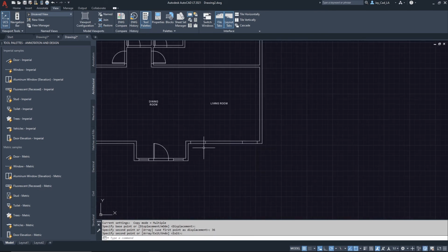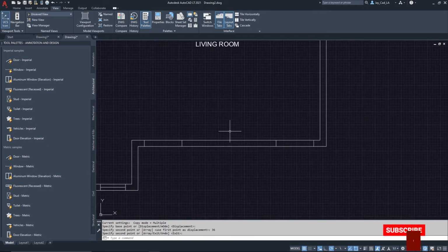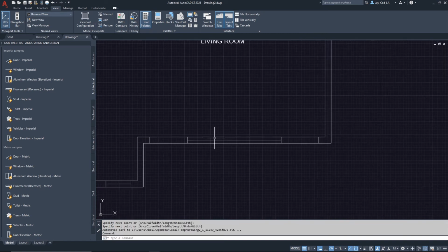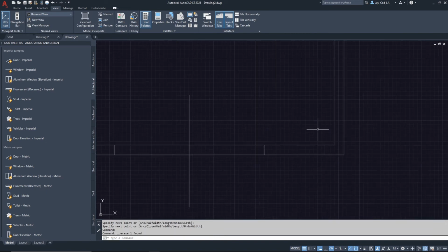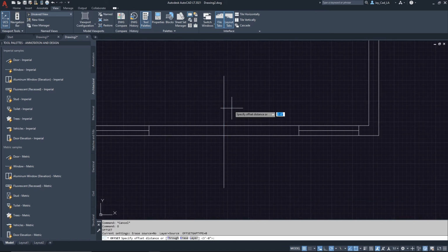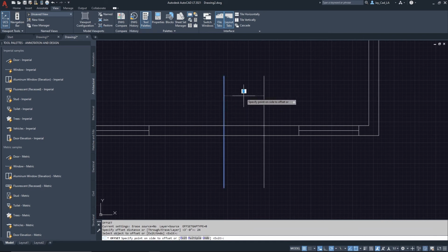Let's say we have actually a fireplace over here. Let's do a polyline here to indicate the middle point. So this is the middle point of this entire segment, but I want the middle point between these 2 windows. So what I'll do, I'll indicate it over here, and then I'll indicate a vertical line like this. Okay, and I'll get rid of this, and I'm just gonna add the glazing to the windows. Okay, and then this line right here, I'm just gonna offset it by 2 feet, 1 tab to the right and 1 tab to the left, and then I'll get rid of it.